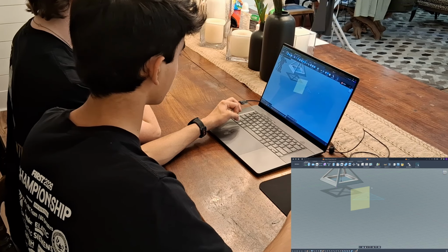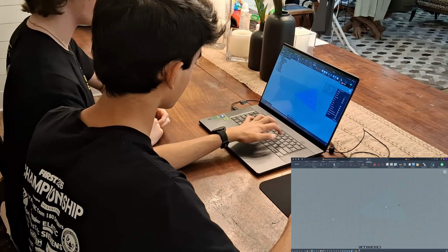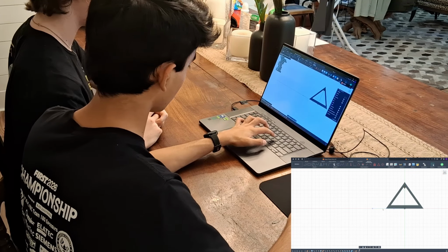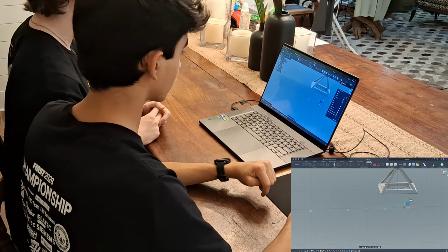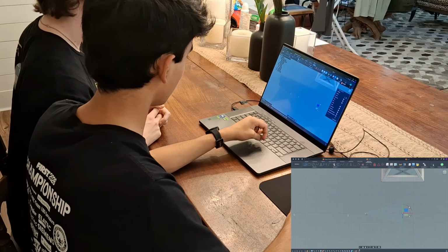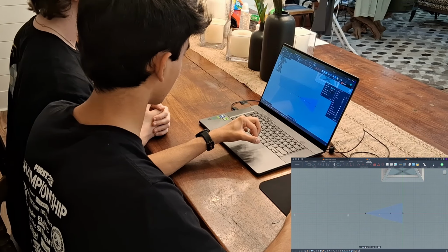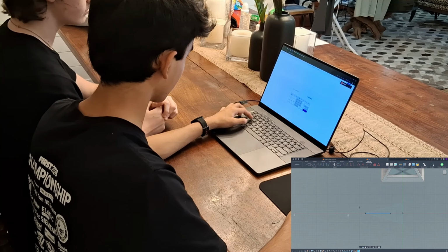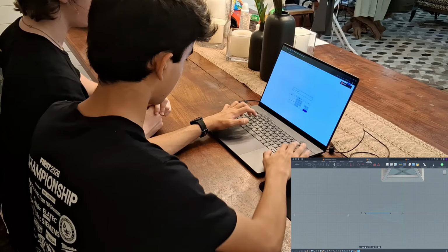I'm gonna go through all these steps again since you've done this. So I'm gonna go over here, make sure you project that middle point and that edge point. So now remember, your side length is 1, that's your c squared, and then now you need your a squared. You know your a right here, you can measure that, it's like 5.7. So if you come over here and measure that, copy that into our calculator, and now instead of doing all that work again, you can just paste it right into here. And make sure you delete the inches.